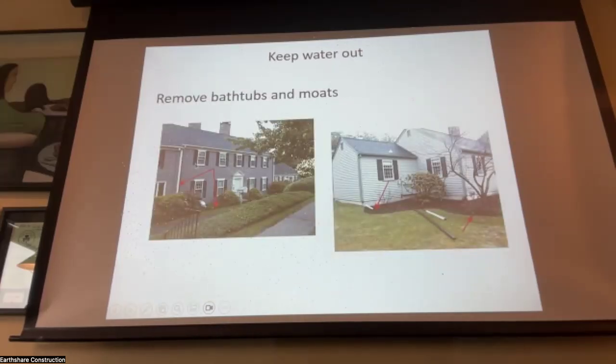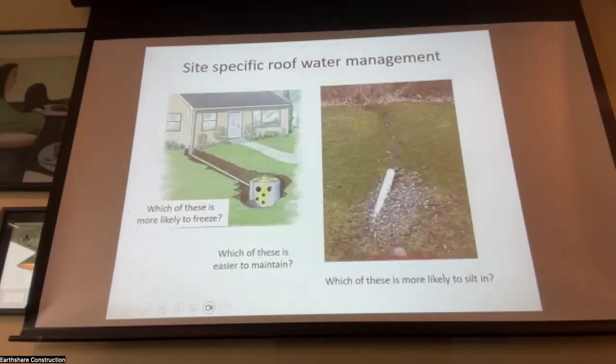This is the building that's right in the brook, right outside of Boston, actually. And all the landscapers go around and dig out all the dirt, everything that might be relatively impermeable. They fill it with chips, which is very permeable. And they put these little short pieces of downspout projections that run the water right into the bathtub. And this water all runs down and into the crawl space. So you want to extend those if you can beyond the bathtub, but ideally you don't want to create the bathtubs in the first place.